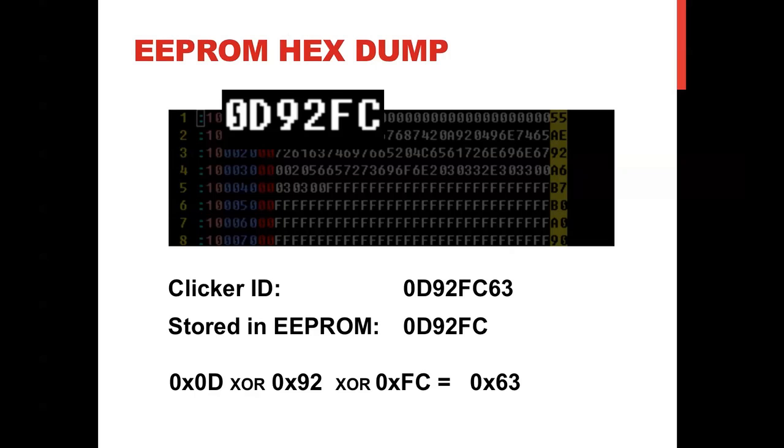So, now that we knew where the clicker's ID was stored in EEPROM, and we knew that we could change it by reflashing the EEPROM memory contents with our programmer, we could do all kinds of things. For instance, it made it trivial to clone a given remote. Say you had an instructor's remote ID. We could make an exact replica of his remote by simply writing his remote ID to our EEPROM memory contents. This would allow one to, say, hijack control of clicker question sessions or even PowerPoint presentations, as some instructors do in fact use their iClicker remote as PowerPoint controllers.